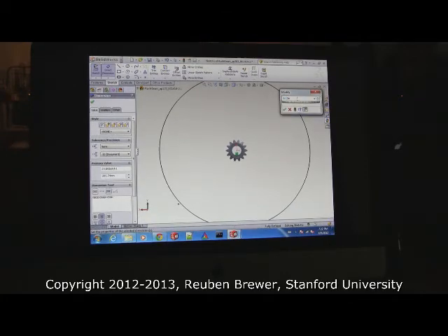So now double click it. You see how it says inches, IN? Divide 25.4. Now before you hit enter, a note. Almost every single place in SolidWorks where you're able to enter a number, you can enter an equation. Now, we're not going to be doing variable equations where we set x and y and we're doing cotangents and stuff. But I always do stuff like, this is a good one, watch this.